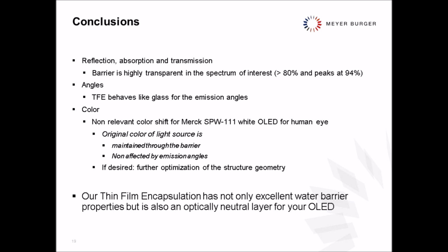So, we are now at the conclusions. We have seen data for reflection, absorption and transmission, and we concluded that the barrier is highly transparent in the spectrum of interest. It is more than 80% and it peaks at 94%. For what concerns the angles of light beams, the TFE behaves like glass for the emission of angles.